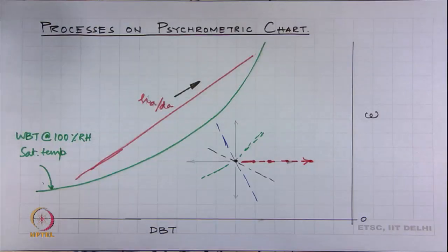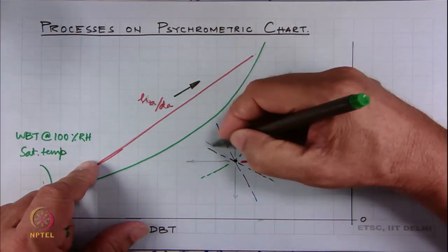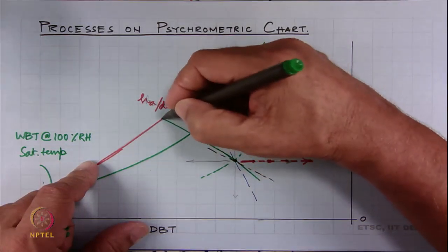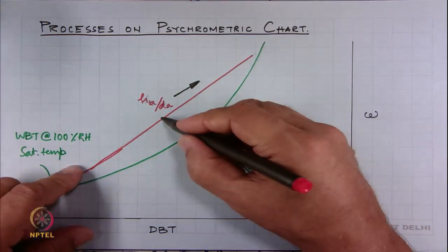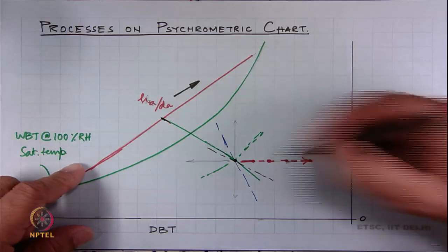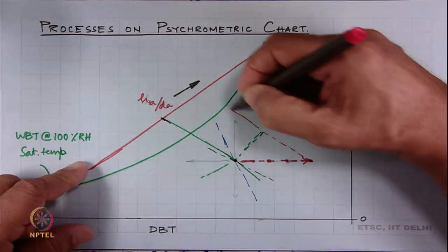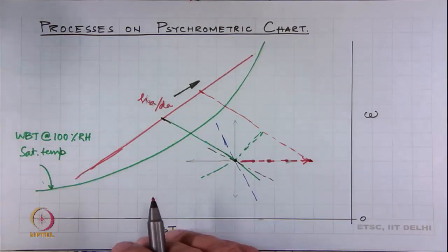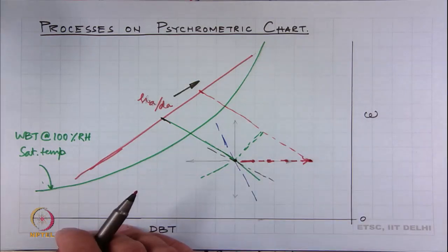So, that is the first application process that we are looking at. What we are saying is that we can get the enthalpy of this state by going to this graph and reading it from there. For the final state, we see which specific enthalpy line goes through it, and this difference is the change of enthalpy during this process.